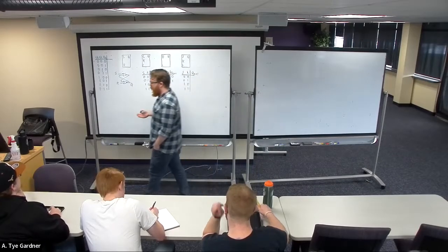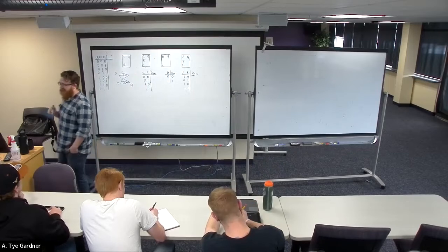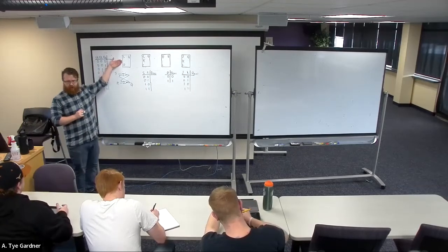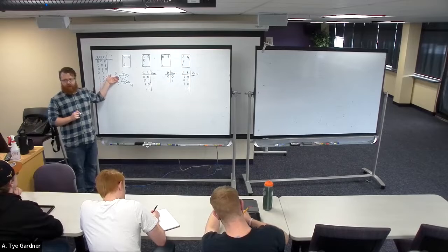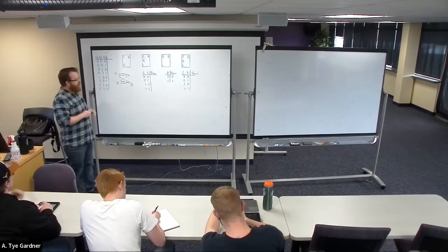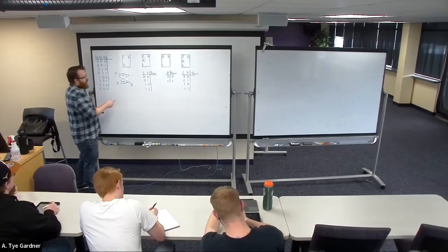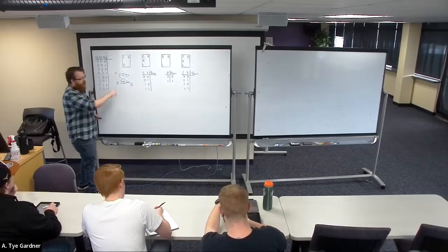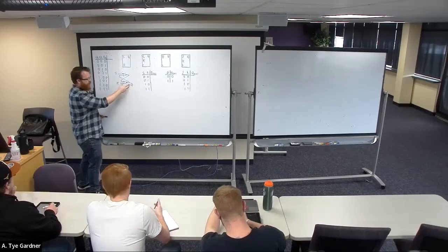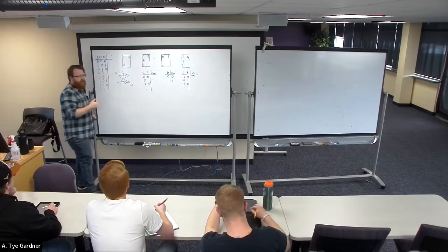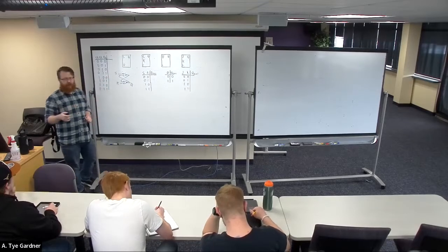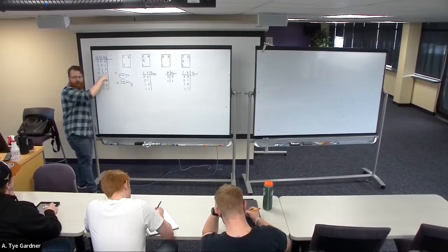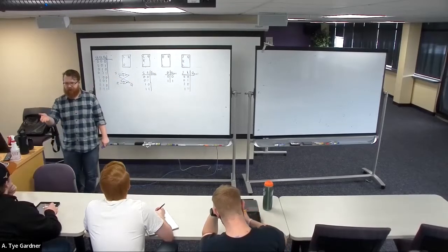And so the base building block we have is the SR latch, which as a component we would draw like so. We would build it out of NOR gates like this. And the idea is basically that if set is 1, it sets the Q to 1. If reset is 1, it sets the Q to 0. If they're both 0, then whatever it used to be is just going to sit and chase around this interloop network, and it's going to hold on to that value.